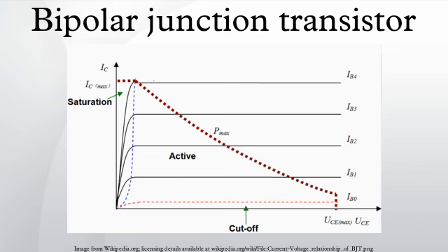PNP. The other type of BJT is the PNP, consisting of a layer of n-doped semiconductor between two layers of p-doped material. A small current leaving the base is amplified in the collector output. That is, a PNP transistor is on when its base is pulled low relative to the emitter. The arrows in the NPN and PNP transistor symbols are on the emitter legs and point in the direction of the conventional current flow when the device is in forward active mode. A mnemonic device for the PNP transistor symbol is "pointing in," based on the arrows in the symbol and the letters in the name.